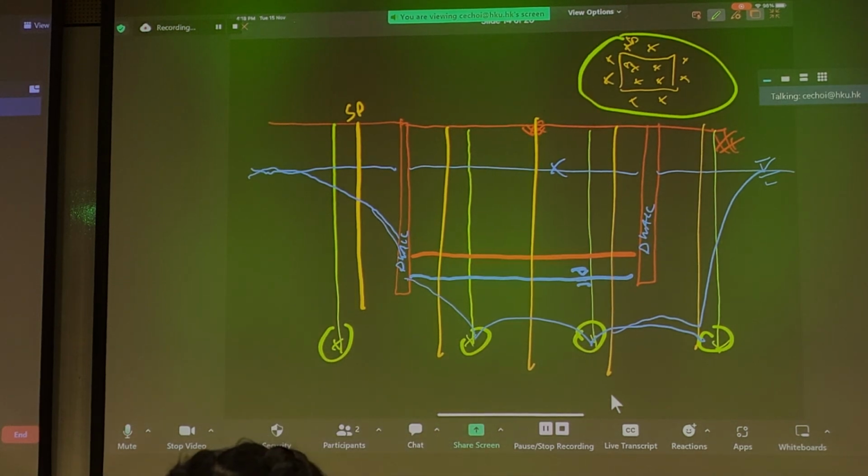And you need to look spatially around this pumping test site. Are there enough pumps in certain locations? Are some locations really pervious? So let's say there's an inability to draw down the groundwater table here because the recharge is too high. This may be indicative that your sheet pile wall has a huge hole in it, right? Sheet pile walls rely on the mechanism of hooking each other, each component, right? There could be a gap, maybe there's a core stone, and there's a huge hole in your cofferdam.